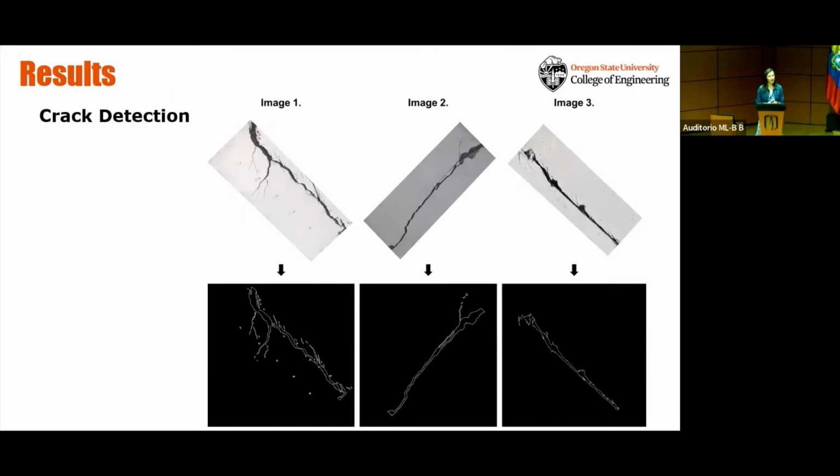That's a good question. For that, the drone flight planning is very important. There are methods where, when you're planning your drone flight, you first take a whole bunch of images, and if you see there are some cracks or other spalling, it's better to take images closer so the resolution is higher. Otherwise, this method wouldn't really work that well.